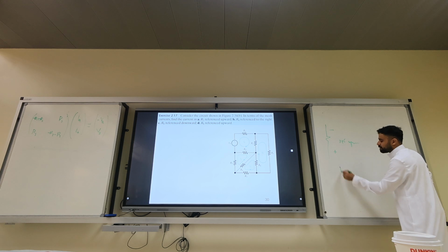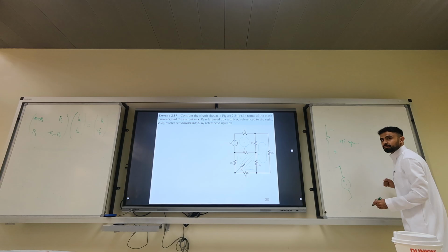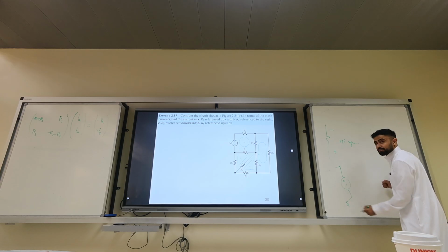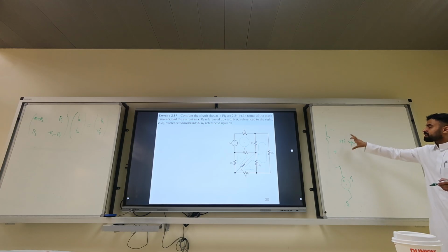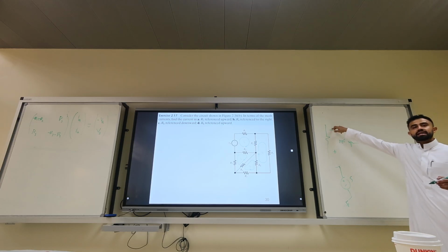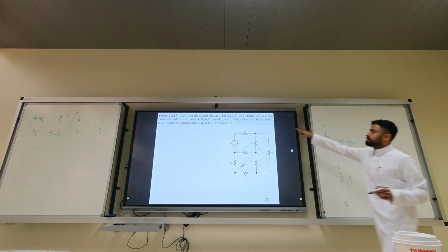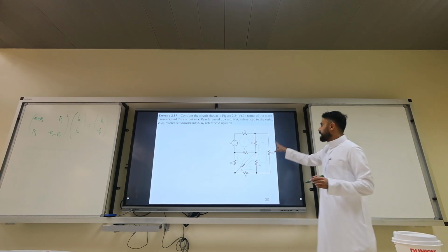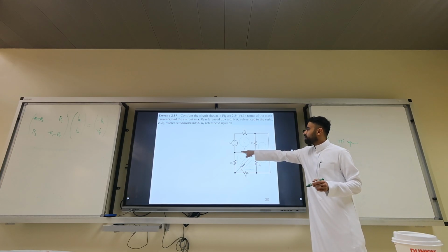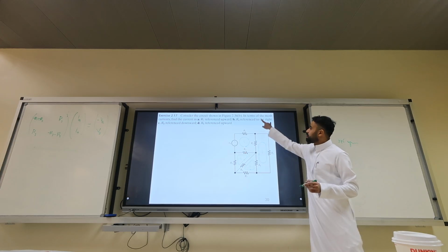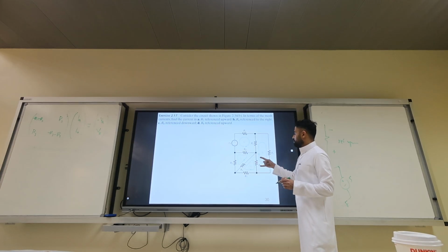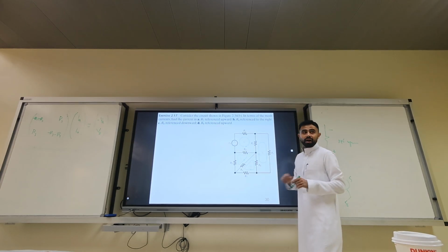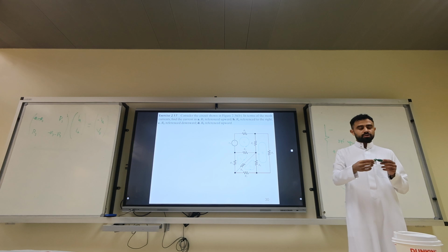It's similar when I tell you the battery has 5 volts. Where is the reference? Reference is here. Right? This is the same language. So for the resistor, when they say reference, it means the negative. Here, reference on the right, R4. Where is the negative? Plus, minus. Here, reference downward. Plus, minus. Clear? This is a confusing language in the book.